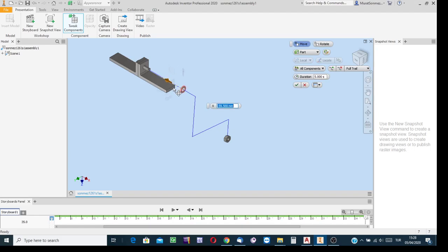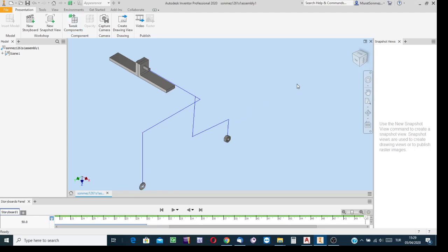Hold it and move it in this direction, then hold this arrow, move it in that direction parallel to the y-axis, and then move it in this direction. Imagine that there is another basket to collect the washers, or another table to put the washers onto. These are the tracks, the paths along which the robot hand is to displace the selected component. And then click on the OK button.